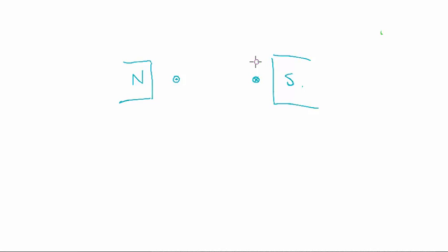I cause the thing to turn. In this case you can see here, here's my field pattern. And at this point here, I am pushing it up. So if this is my magnetic field, I'm causing my wire to move perpendicular through a magnetic field, which means I am causing a current to flow in here.